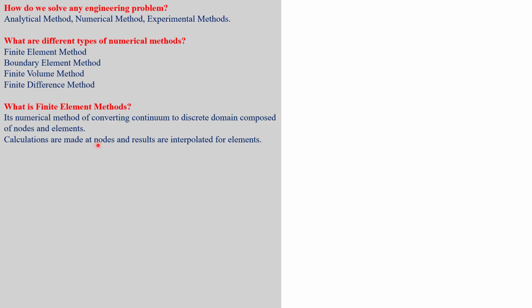Let's say you would like to know the stress results on a particular element. If I consider a rectangle, this white area, I'm going to divide it into different elements. For this area we'll have 4 nodes, one here, one here, one here, and one here. Now if you would like to know the stress results, we can't have them on the nodes, so we'll average them, the von Mises stress, and you're going to get it on this complete element. So we see the elemental stress. Likewise, we get the results interpolated on the elements. So this is the example.